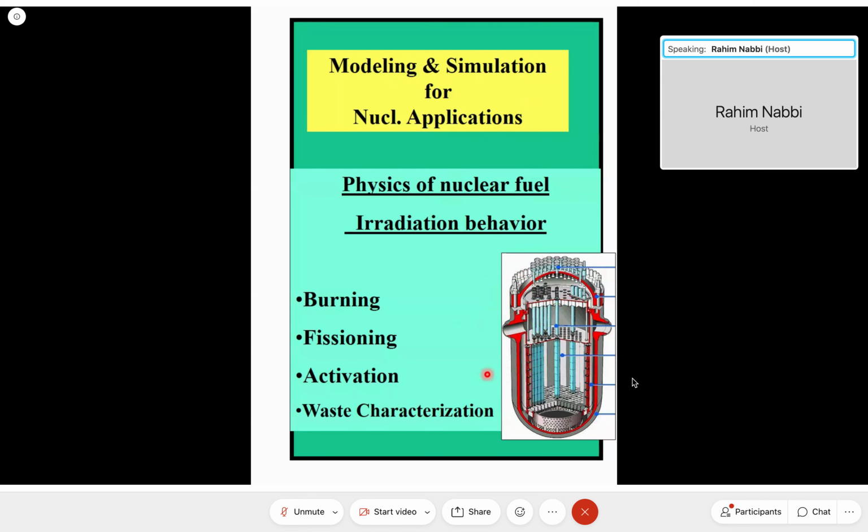The big topic in this case is the characterization of the waste produced. We have heat-producing waste, everything with the fuel, because you produce actinides and partly fission products. The other groups, mainly a result of activation, would be the activation of structure components, and so on.